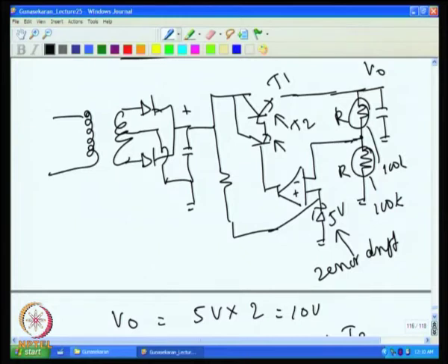Then similarly, the bias current flowing through will have an error, because there is no equivalent resistance on the plus side, and the bias current has to go through this. So, when the bias current drifts, the current flowing through this changes, consequently the voltage across this changes, and the output also will have an effect.